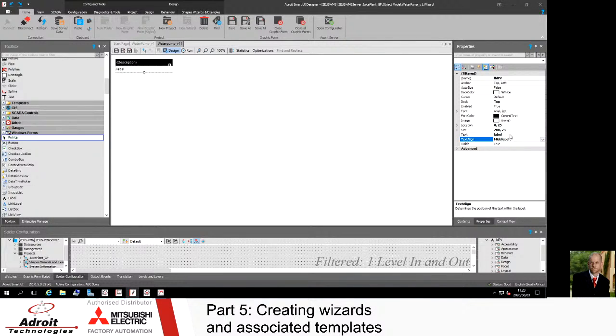So one of the things we can do here as well is this guy's going to have a dynamic substitution in him. So I like to put in my label field what I'm going to be showing there. So in here I'll put a PV space, and then we'll put in typically how many value or characters I'm expecting to use. And now I've got a good example of what I'm really expecting to see on my graphic. And guys, obviously this will be overwritten by whatever dynamically I change this.